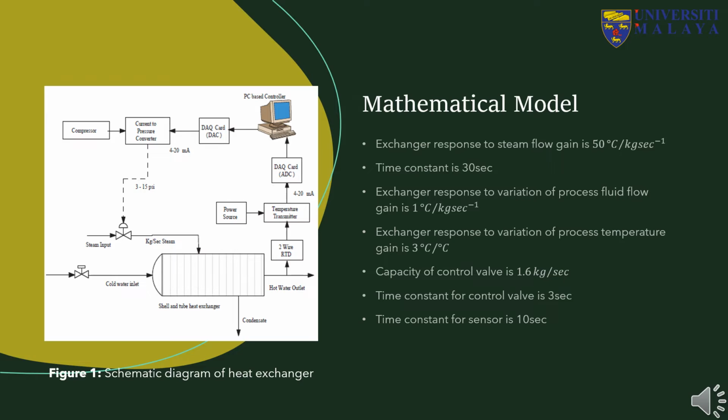And the capacity of the control valve is 1.6 kilogram per second. The time constant for the control valve is 3 seconds. The time constant for the sensor is 10 seconds. From this experimental data, a linearized mathematical model of the heat exchanger is developed.